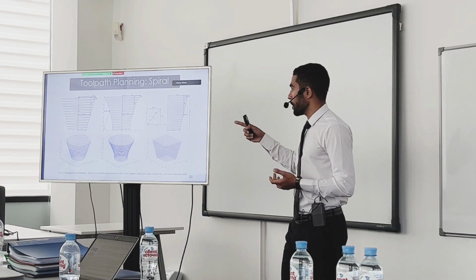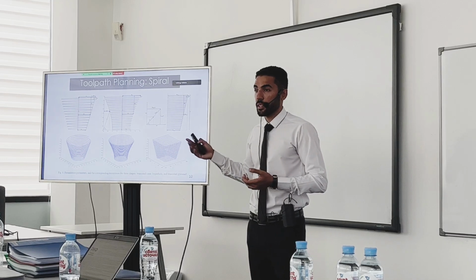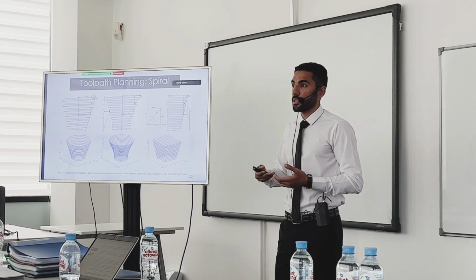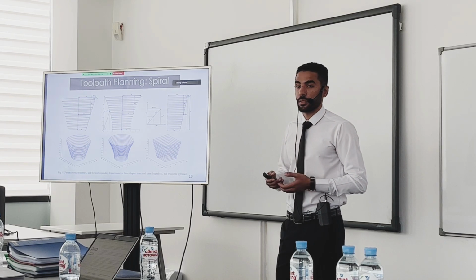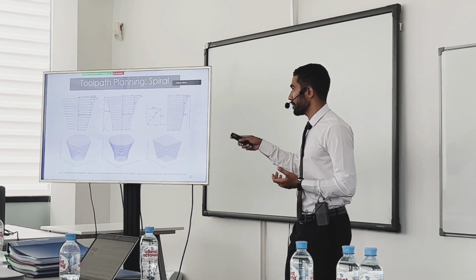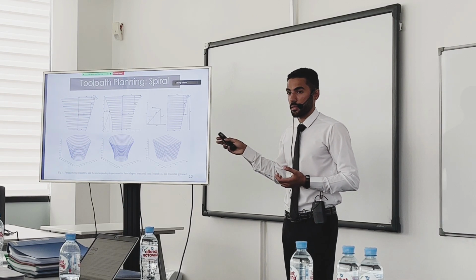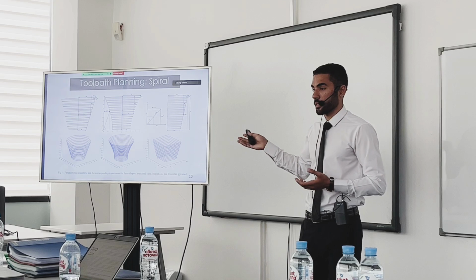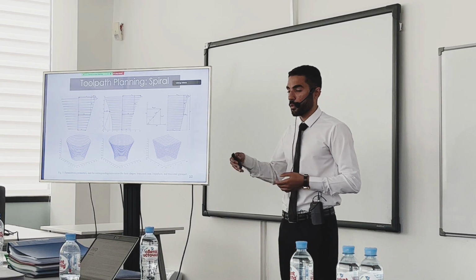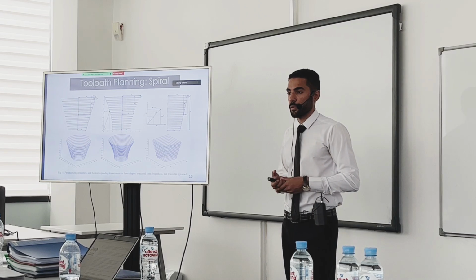The second point, about complex geometry: the advantage of incremental sheet forming is that it can do shapes that have undercuts or complex 3D geometries, but I didn't simulate these shapes in this part, but I'm trying to go further and test one of these shapes.